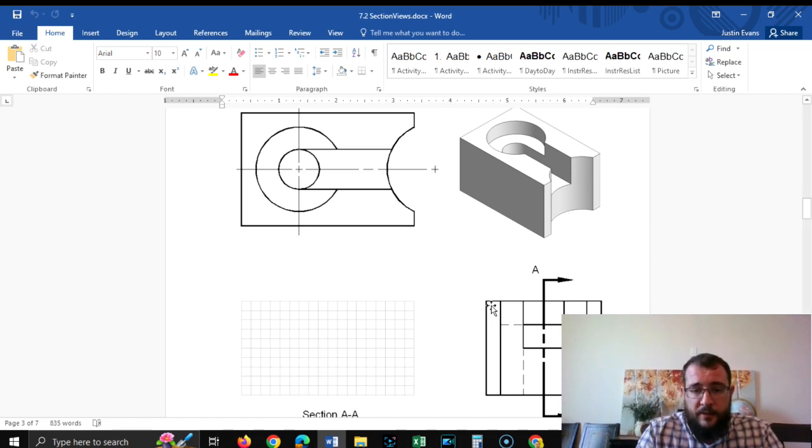Now I can use that to figure out how tall this is and where this cut is and where the diameter of this is and how wide this is. In the other dimension, you can take a piece of paper or a ruler, line it up to your paper, find out how long that is on the paper, and then put it up against the squares. Most of these things seem to fall at about a square or a square and a half for sizing. Which means everything is 1 inch, an inch and a quarter, an inch and a half, an inch and 3/4, 2 inches, and so forth.